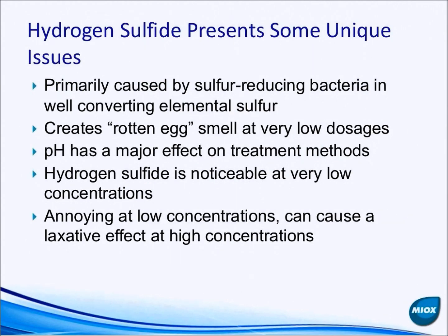So keep in mind, when you're talking to folks about manganese reduction, you're going to also want to make sure that you're speaking to them about what sort of filter they're choosing, and that becomes a very important discussion point with them. I should say, if they're already talking about using something like a green sand media, then you should be fine. If they're not thinking about using a coated media, then I would strongly recommend it to them. It will make the system work much easier and be much more likely to succeed.